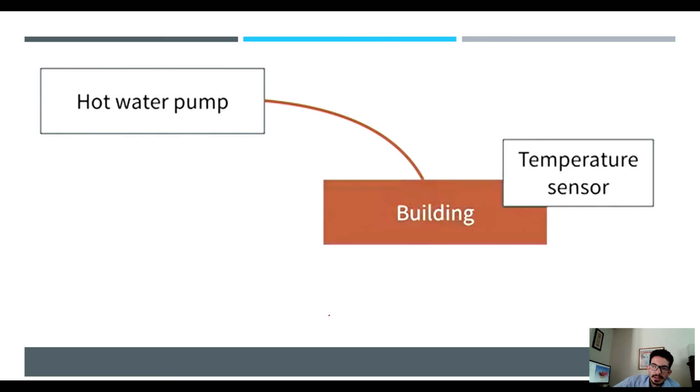Another very common application is, as I said, compressors, where you want the temperature of the building to be controllable, or the temperature in your refrigerator. And then by giving you more mass flow of refrigerant, you can get colder temperatures in an instant. Or if you want a water pump, then you can vary the speed of the pump or the pumping by varying the pump velocity with a drive.